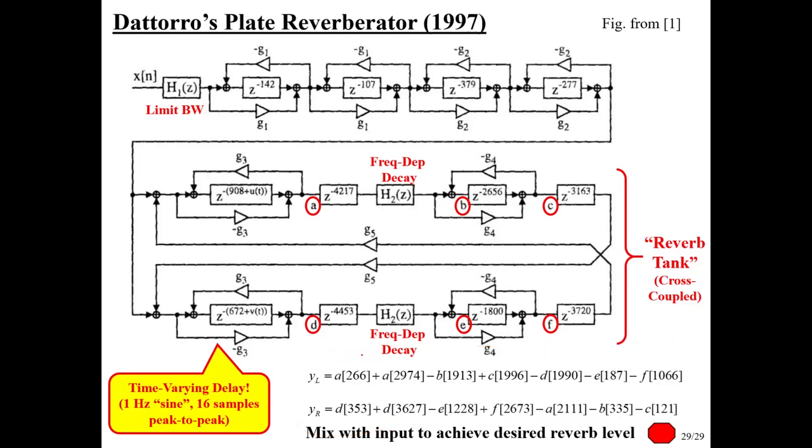But these are just relative delays at those positions. So it would really be like n minus 266 or something like that. There's more detail probably in Gardner's paper and certainly in De Toro's paper. But basically we're tapping off at 6 different places with different time references and adding and subtracting those things.